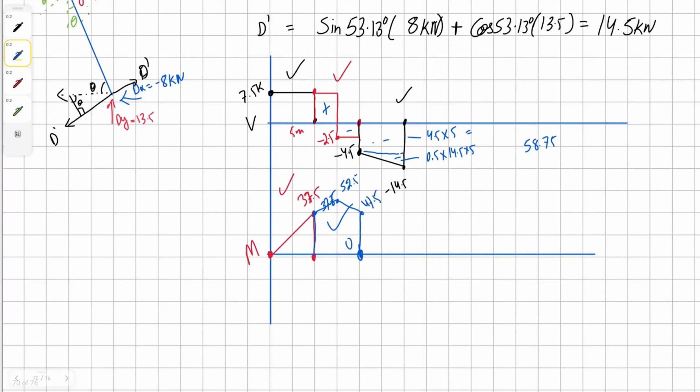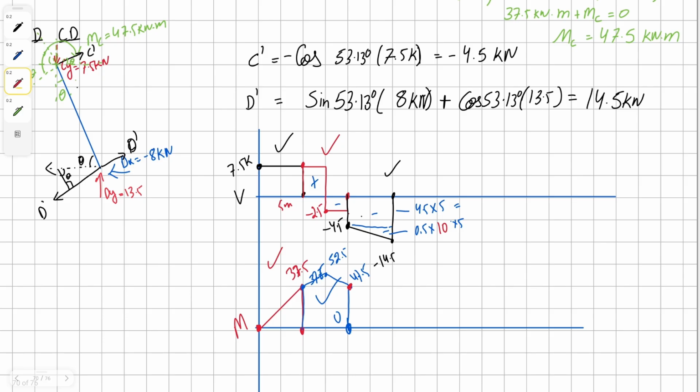So we're going to go upward 47.5. And from 47.5, we're going to go downwards. Any mistake I made over here when I was letting you guys know what the area of a right triangle is, that I mistakenly added here 14.5. In fact, it should have been 10. So that has been corrected. And adding these areas together, we get a solution as negative 47.5, negative because our areas are negative. So that brings us all the way to our point 0, and in this case our curve is concaving downward and it's going to be a second order curve, and that means our